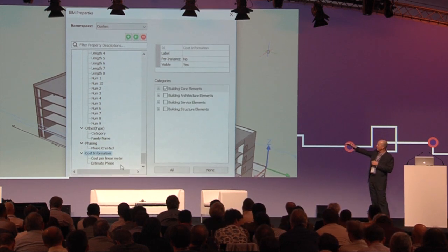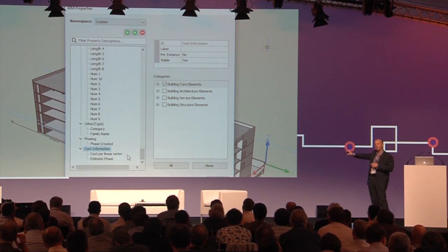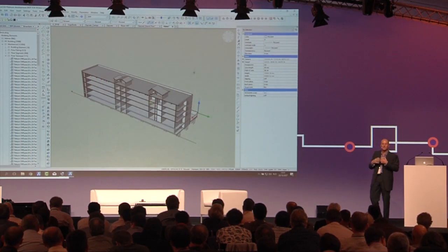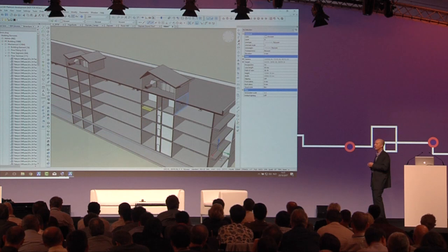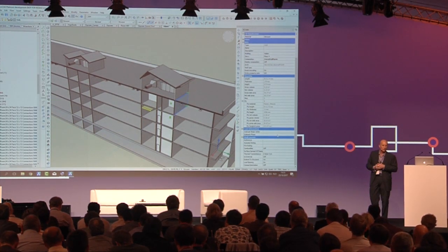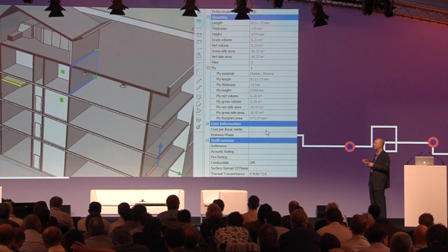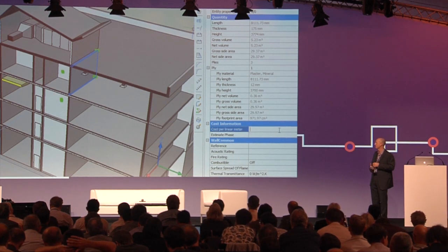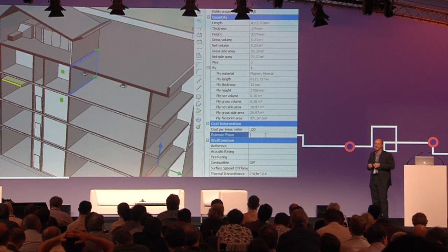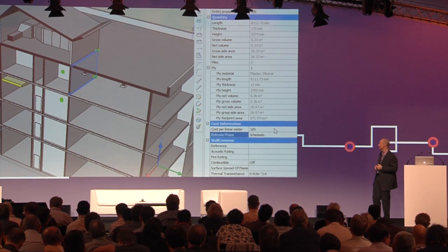So once we've created those, at the bottom of the property list, we have that property set, and we have those 2 new custom properties. So we can hit OK, and we can go back to the model. And then now if we selected a wall, we could go to the properties of that wall, go down to the cost information category, and then now we could include a cost of maybe say 100 per linear meter, which is probably under, and an estimate phase of, we say schematic design, since we're still early in design phase.